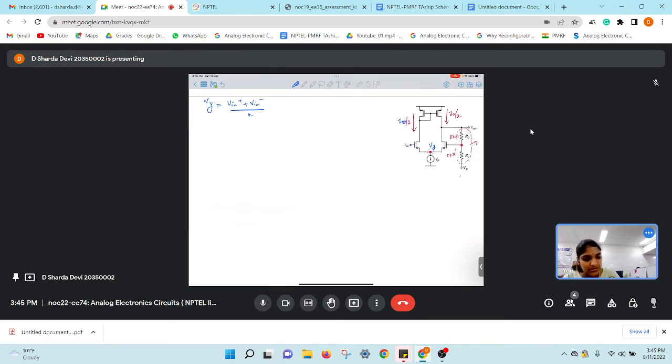Vn plus is how much? It is actually Vin. Vn minus is how much? It's actually connected in the feedback path. So if this node is my Vn minus, how much will it be? It will come by superposition of Vout and VB.